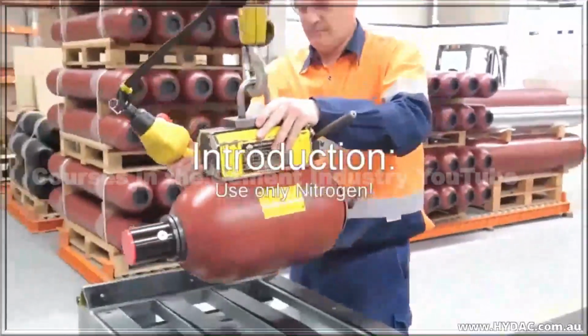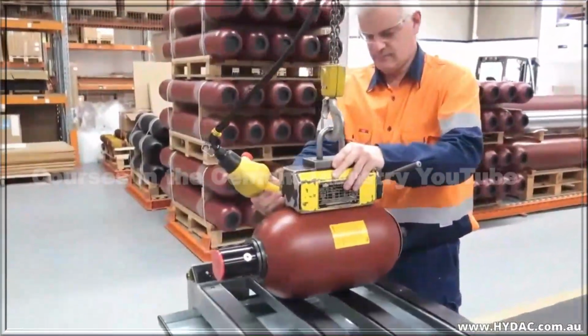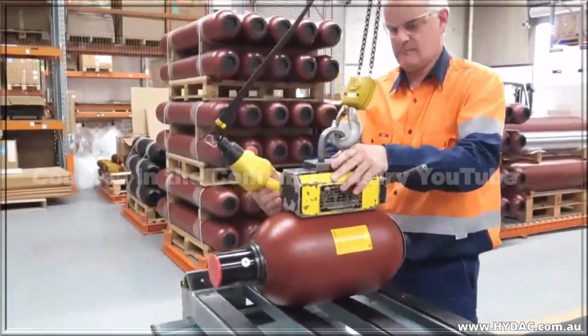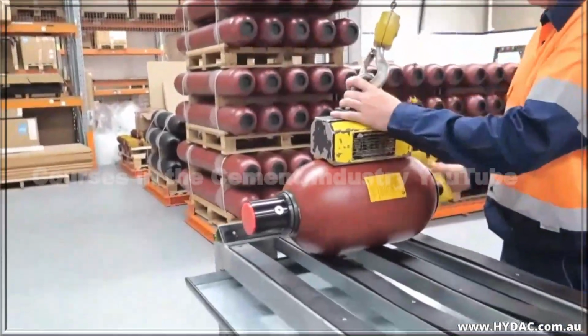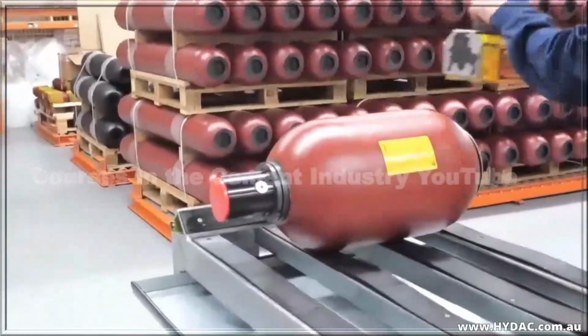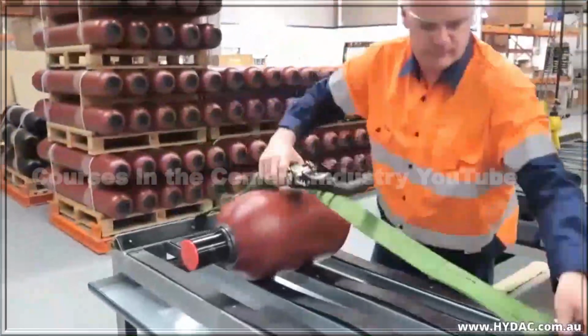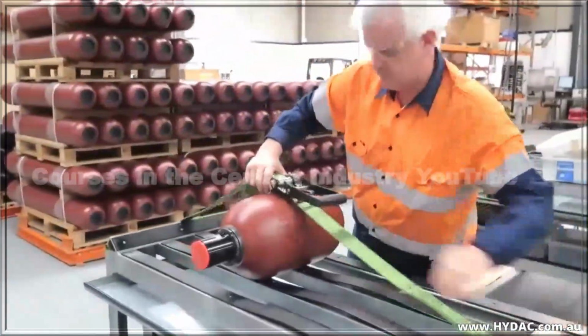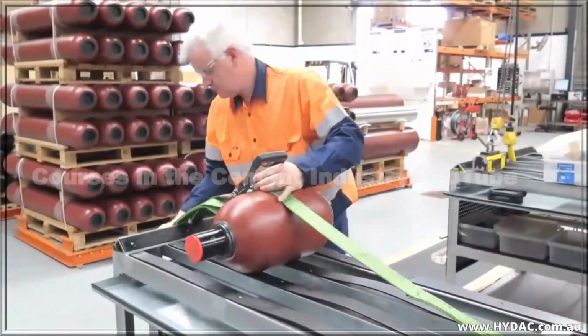Hydro-pneumatic accumulators need to be pre-charged with an inert gas in order to work at all. Selection of the correct gas pressure is vital, as it defines the stored hydraulic fluid volume and pressure, which are important for the safe and correct operation of any machine. It is important that the correct gas pressure is maintained, and periodic inspection is therefore necessary.